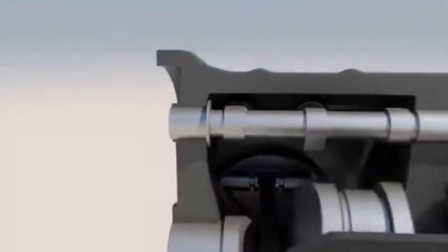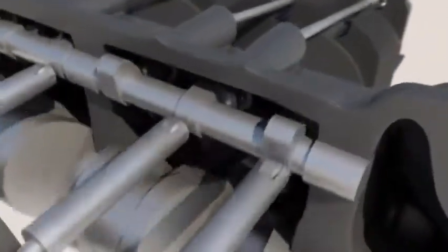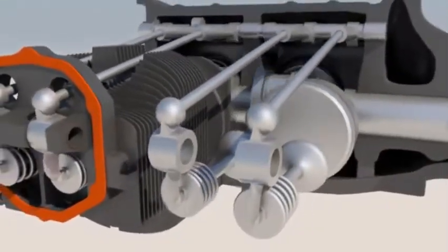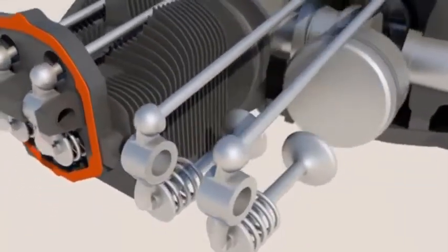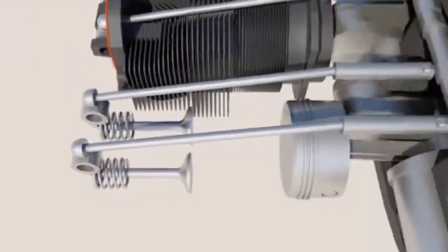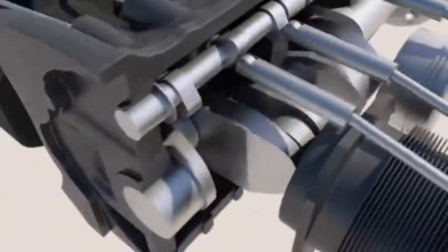The camshaft is a rotating cylinder situated above the crankshaft with various oblong lobes protruding from it. These lobes push on rods that connect to each valve, pushing them open. The valves are spring-loaded and will return to the closed position as the camshaft lobes move away from their respective rod. Getting the valves to open at the exact moment is very crucial for the engine to operate.